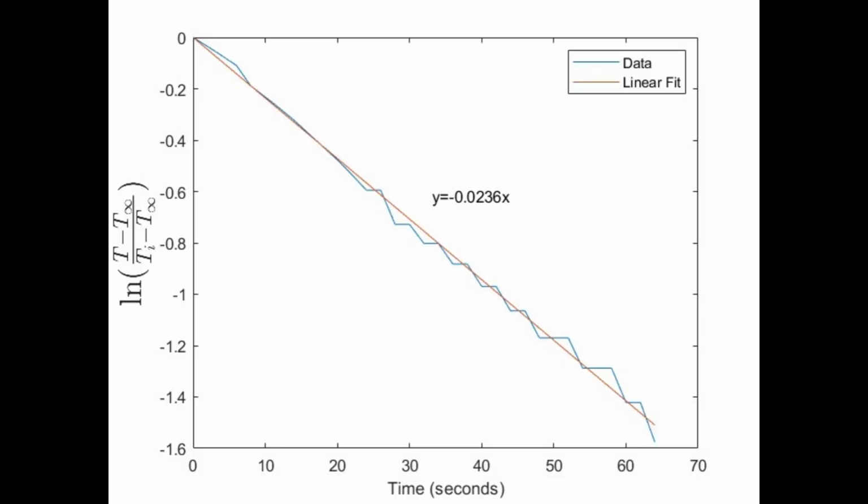The biggest contributor to error is the probe itself. When measuring the temperature of boiling water, it was 4 degrees below where it should be. Additionally, the temperature displayed by the probe seemed to be lagging behind the actual temperature. At the beginning of the experiment, when the probe was put into contact with the sheet, the temperature went up instead of down because it was catching up with the actual temperature.